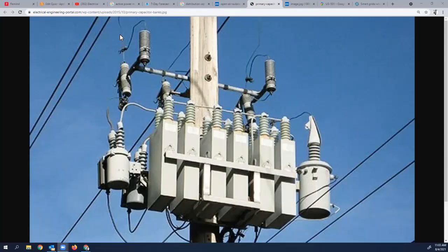As soon as I put voltage back to this bank, I know the vacuum switches are open and I've got a green flag. Before I put anything back to it, go ahead and cancel that hotline work permit, close your switches, and go through the whole process of putting your bank back in service. Just in case you do have a failure, the breaker is going to be automated, so you're not going to have everybody's power out in that process. Then give up your hotline work permit. A lot of people forget that one step. So when do I cancel the hotline work permit? It's going to go in the process right here.